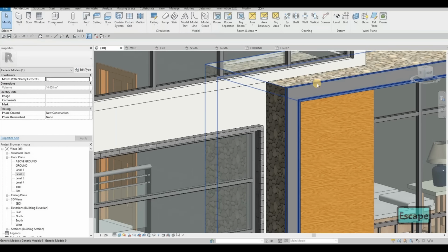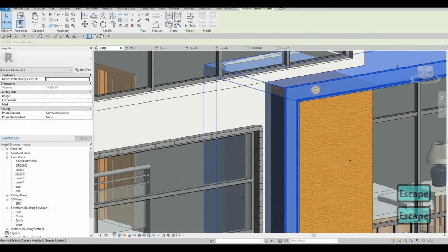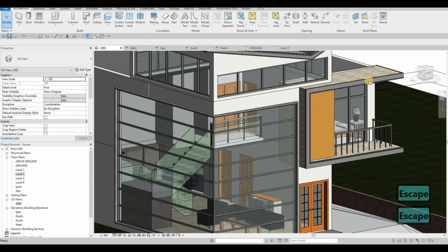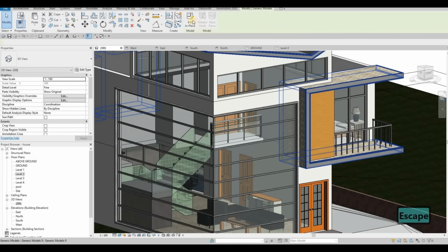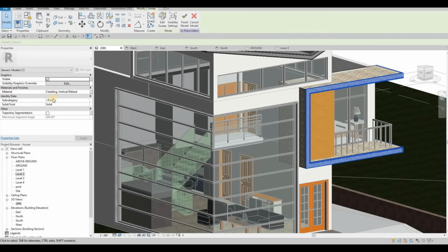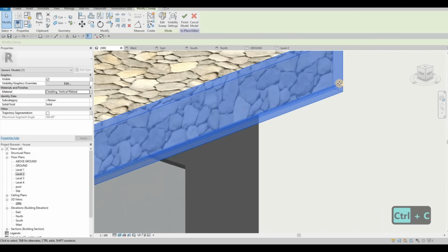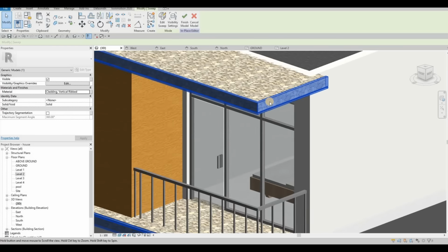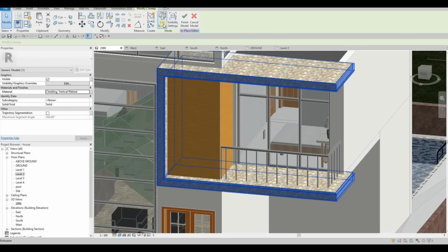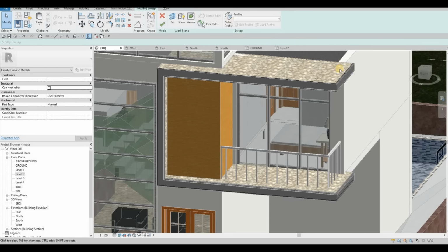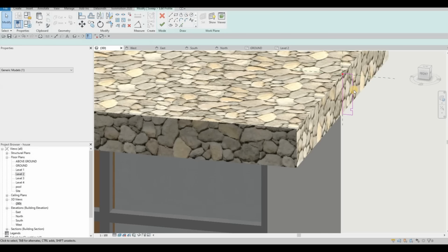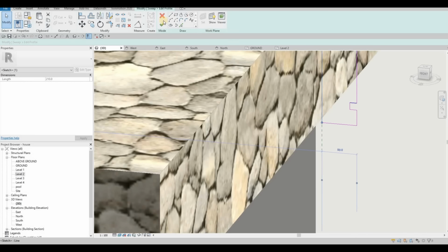And then we need to add this one as well. So let's save it first. Edit in place. Select this one. Cladding, Revit. I'm gonna copy that. And then add this one right here. So I'm just going to edit profile. So this is 50, and then the thickness, and then just adding a notch on this one.